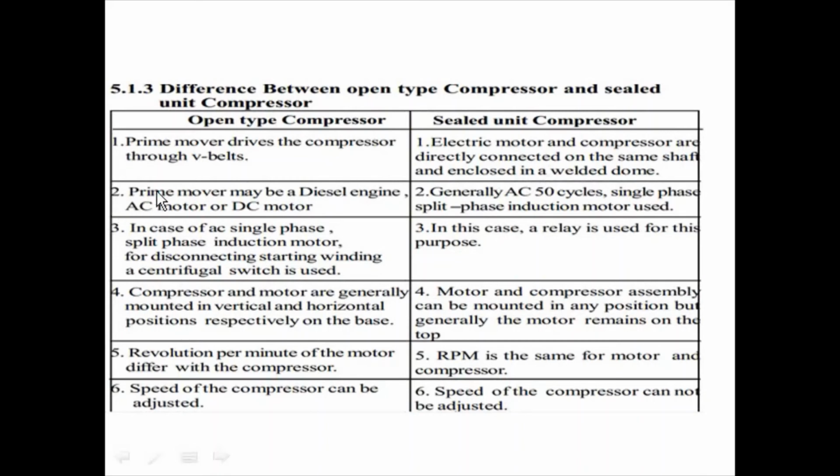For open type compressor, the prime mover may be a diesel engine, AC motor or DC motor. But for sealed unit compressor, generally AC 50 cycle, single phase, split phase induction motors are used.